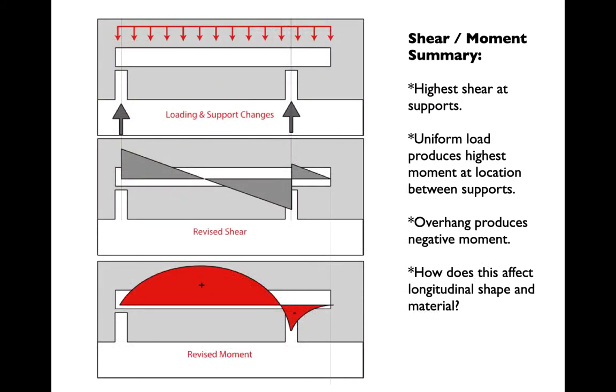So what's the problem that we're trying to solve? Well, if we go back to our shear moment diagrams, remember we were looking at loading conditions, looking at reactions, doing our thought experiment where we were going left to right, tracking through what the internal stresses in a beam would need to be to resist the forces to one side or the other. And when we got down to moment, we found ways to calculate the maximum bending moment in a beam given what we knew about the shear. And remember that the maximum moment here is going to be equal to the area of the shear diagram up to that point. So now we want to figure out how a beam actually resists those moments. Once we've figured out the maximum shear and the maximum bending, what properties in a beam do we have to work with that allow us to resist those moments?